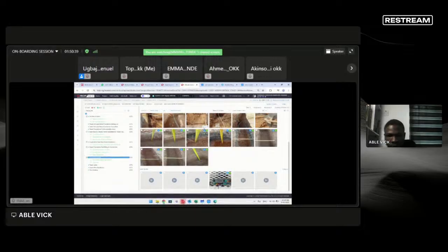So for the point testing, you'll be testing the tower leg, you'll be testing your cabinet bus bar, and you'll be testing the earthing ring. You can pick a point on the ring and test for it to confirm your earthing values.